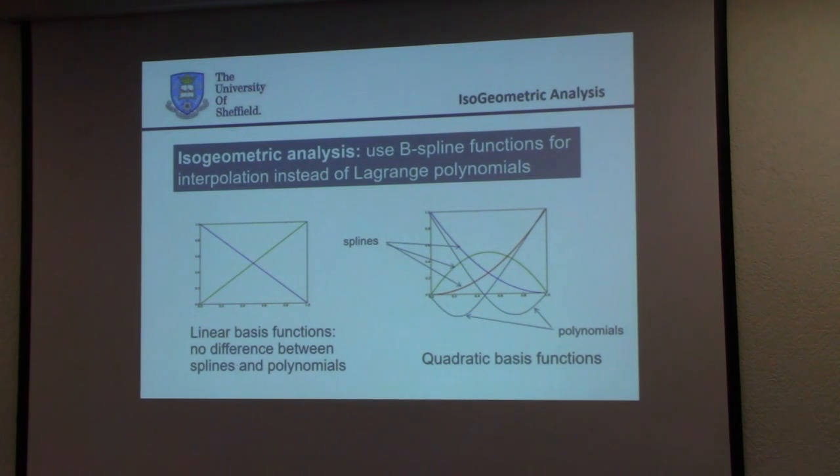Now there's one thing which you immediately see, hopefully, and that is that the B-splines have a so-called non-negativity property. You see, Lagrangian functions become negative here. Higher order splines will not become negative. And especially when you go to dynamic analysis, this is a huge advantage, because when you construct, for instance, the mass matrix using Lagrangian functions, you have all sorts of negative entries there. When you do the same using B-splines, you don't get negative entries. And that gives you much better behavior.